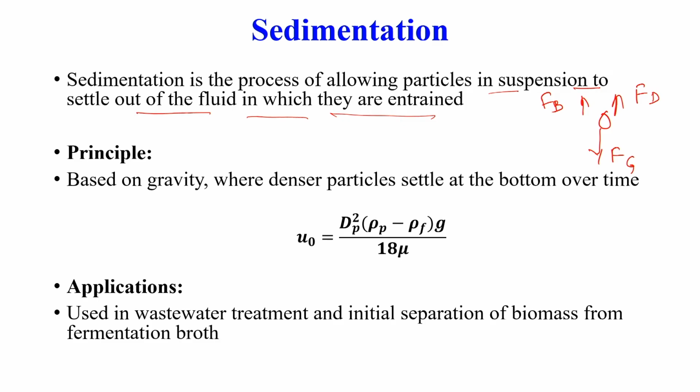Now, what is the driving force? It is based on gravity, when denser particles settle at the bottom over time. You can just see we can apply the same equation over here. The settling velocity is proportional to the difference in density, particle size, gravitational force, and inversely proportional to the viscosity.